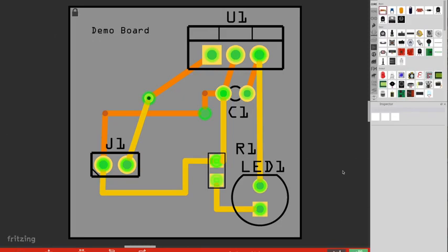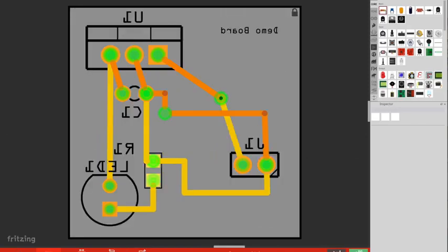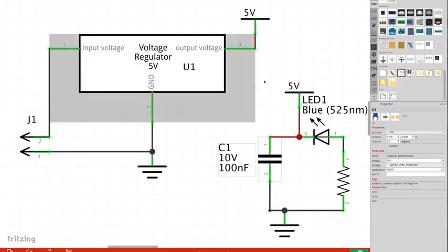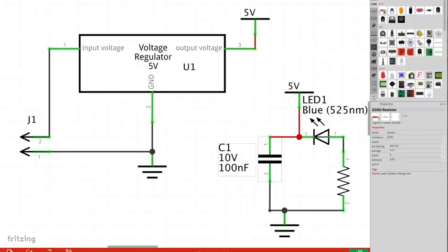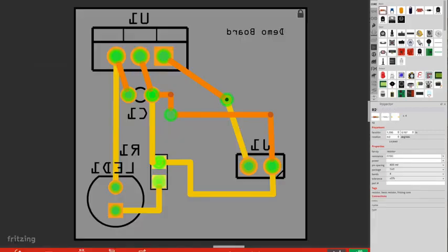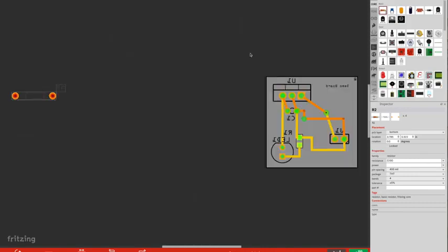Okay, but putting SMD or surface mount devices on the underside of the board is a tad more complex. The first thing we have to do is be looking at the underside of the board. We then go to the schematic and we take a resistor, drop that on there, go back to the PCB, do a Control-0 because I must be up there. See, it's my resistor over there. You will notice that is actually in orange.